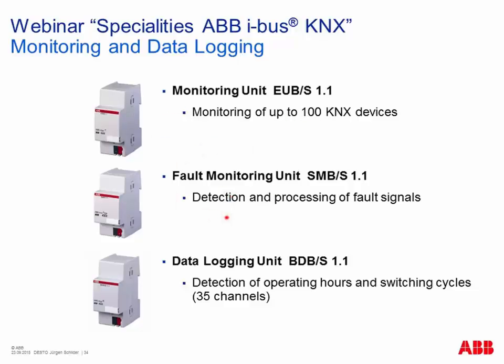Fault monitoring unit, for detection and processing of fault signals, for example in a hospital or any industrial facility. So also a specific solution. And here the data logging unit, which allows you to detect operating hours of selected circuits, power circuits in your KNX installation, but also switching cycles. For example, you would like to monitor operating hours of your lighting system in order to replace all light fixtures after a certain time. Things like these are possible with these components.